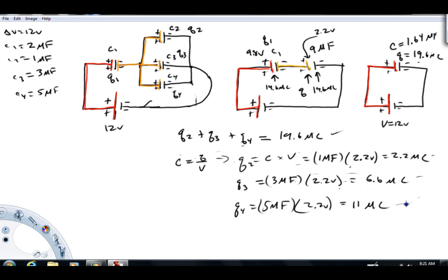I'm reasonably confident. So looking back now at our original problem here, we have the charge and we know the voltage across every one of these capacitors. So again, let me recap how we do that. You take your original, kind of complex circuit, and you identify any parallel or series parts in the circuit. The first thing that jumps out at me is that this is a parallel combination. So for capacitors in parallel, the equivalent capacitance is just add. By the time we add this capacitance, this capacitance, this capacitance, bang, out came 9 microfarads. Make sure you redraw the circuit whenever you simplify anything down.